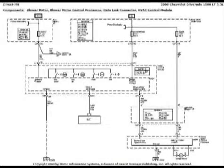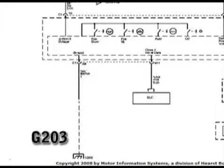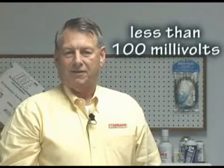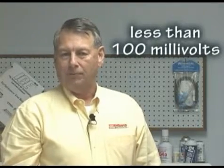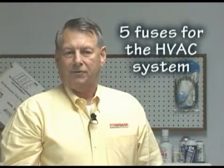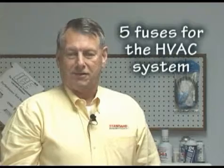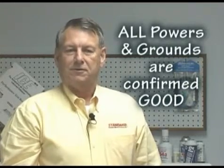Grounds are located at G200 and G203. Voltmeter testing verifies with the engine at idle that these grounds are less than 100 millivolts differential between the ground point and battery negative. On the power side, there are 5 fuses that supply power to the components within the automatic temp control system. All powers are confirmed and grounds are confirmed.